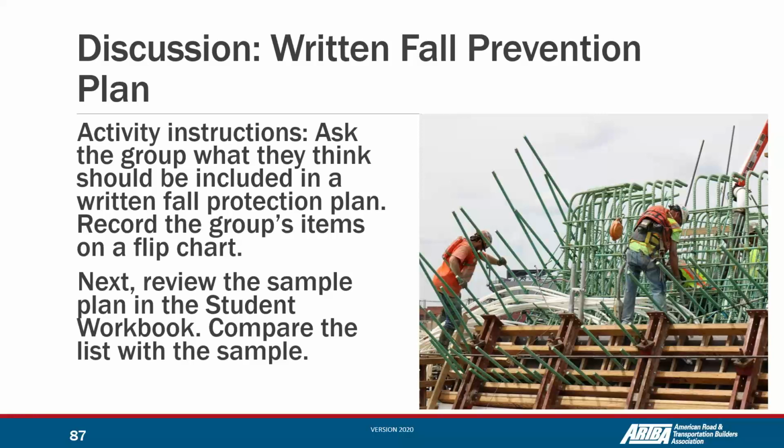Okay, so we identify the hazards, then we need to use our OSHA control safety hierarchy and think, okay, what are we going to do to eliminate the hazard? Maybe you can think, hey, let's build a bridge on the ground level and then use a couple of cranes to put it in the final position. In that way, we eliminate completely the fall hazard for high altitude because the bridge is on the ground level.